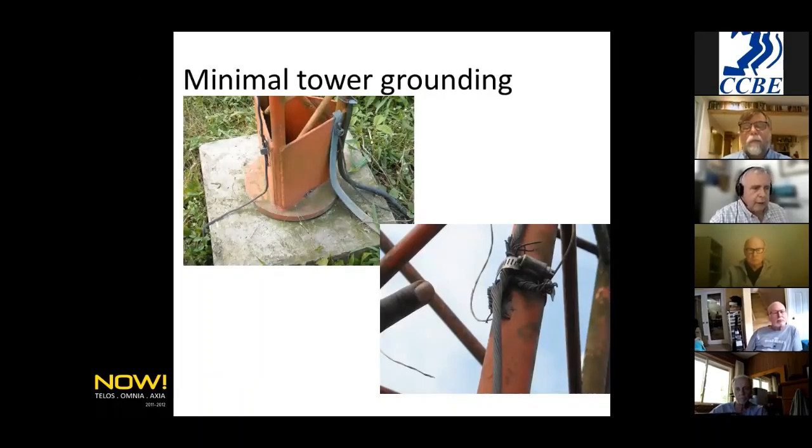This is pretty sad when you think that that wire on the left is the station ground or the tower ground. You can see in the picture below that where they've got a hose clamp and a little bit heavier piece of cable, but that is the ground there. Just got to be really careful that things are done properly, and that if you see this, that you make a correction so that your facilities are properly grounded.